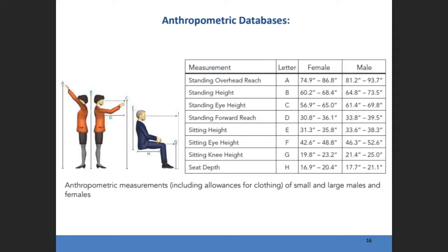tolerance. So we have 60 to around 70 from the minimum in the female. Usually the female will be less than the male as an average, not extremes, because in the extremes it's natural to have a female taller than a male, but in average. So we go with the minimum in the female and the maximum in the male, and we go with the closest number, meaning 60 to 73.